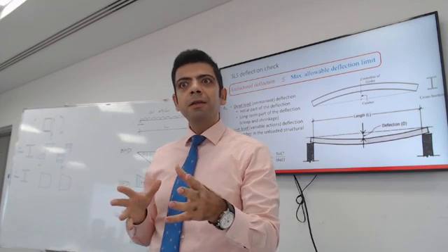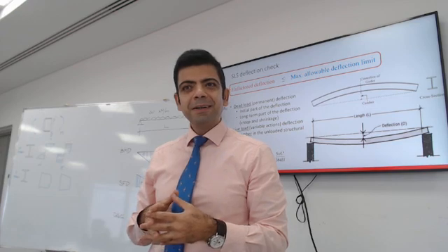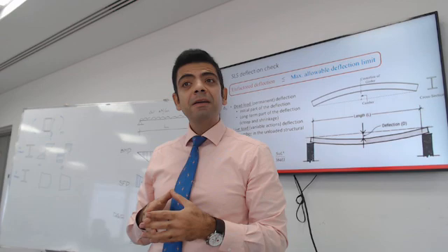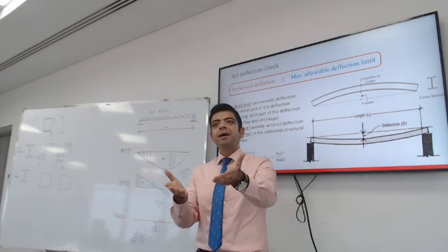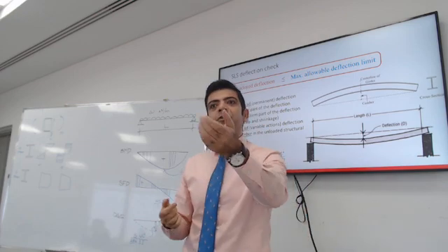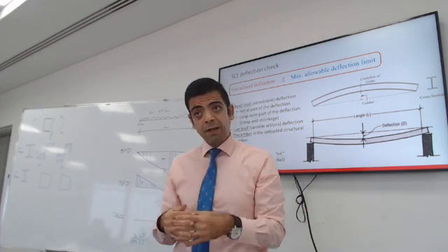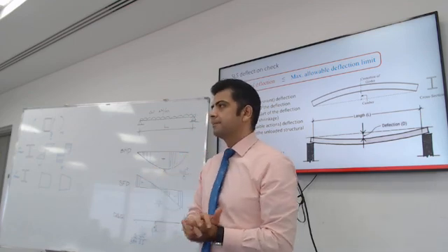Do you have anything to add? So what would you do? Okay, as Omar said. What did he say? He said if there's a lot of dead load, we will use the camber. If it's okay, we will use the original. I would personally tie it to the dead load deflection. If the dead load deflection is very significant, I could start introducing a camber. That's a very good question.